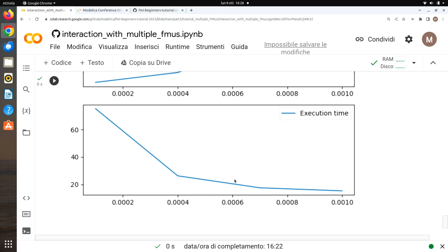And you can also, if possible, run a distributed co-simulation. If the problem is that your system is very complex, you can break it into subsystems, each composed of one or more FMUs, and run them in a distributed environment. You might increase the communication delay between the FMUs a little bit, but then you might solve the problem of your computer's power, because you are adding more computers. Yes.